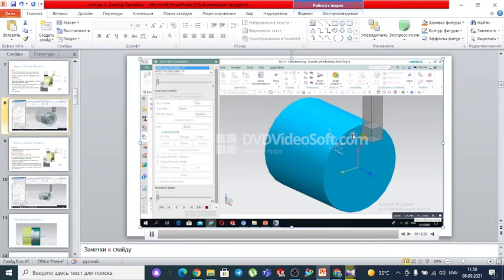In this case, it removes from both sides of the cylinder. This is the facing operation. It is always performed as the first operation for the turning operation. This is the animation made in the NX.